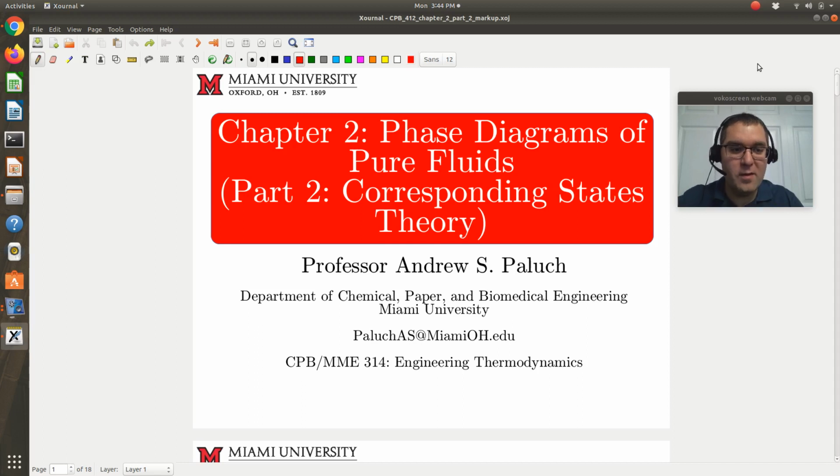So we talked about reading phase diagrams. Now we want to talk about quantitatively modeling, so that when we go on later and solve problems, we can quantitatively solve them. In a typical engineering thermodynamics course, most of the emphasis in terms of that quantitative modeling involves using tabulated data. Tabulated data is great and works well for this course because we'll primarily look at problems involving water, or maybe refrigerant 134A, a common refrigerant. Data is readily available in tabulated form.